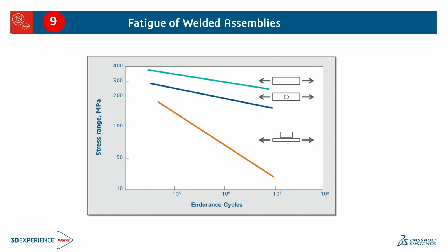Now, I won't get into details here. What I really just want to bring about is you can see that this is significantly lower life and a different curvature to parent plate material fatigue. That generally means you're going to need a different approach in order to get an accurate result for a welded fatigue problem.